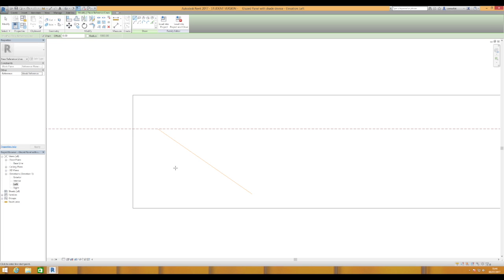This is just giving me some geometry to sort out the louver blades. So if you click anywhere in space near that reference line, get your perpendicular snap coming up and draw a line with perpendicular happening there. I actually want this to be 18 millimeters long. See if that works for me. Yes, it did. So I wanted that to be 18 millimeters long but perpendicular to that line. And then I'm going to pick that one up and move it from its midpoint and find a midpoint here. So I just want a little cross like that, 18 millimeters.